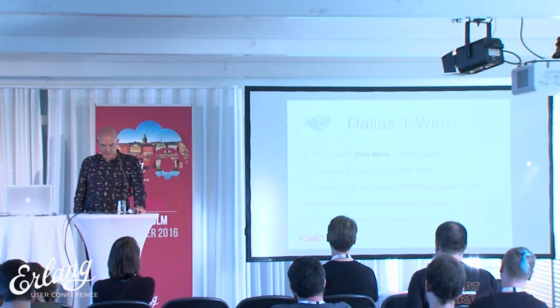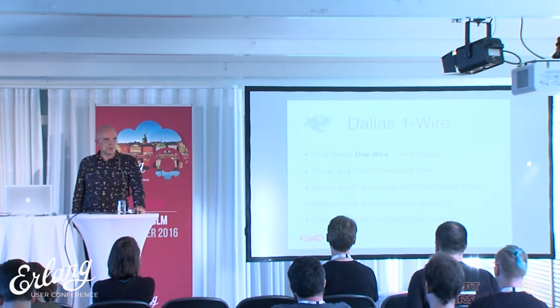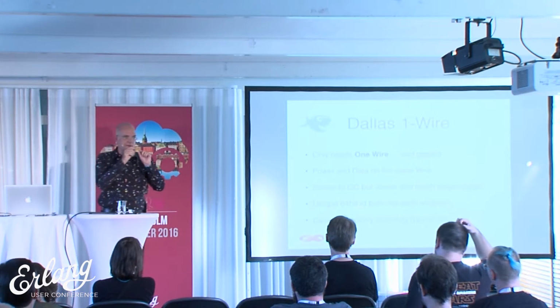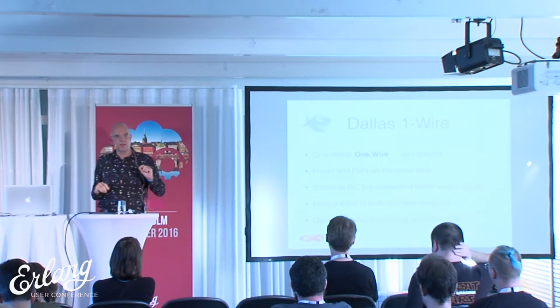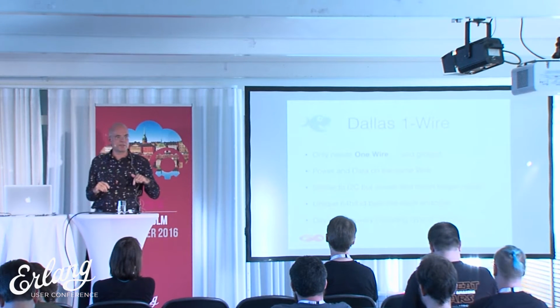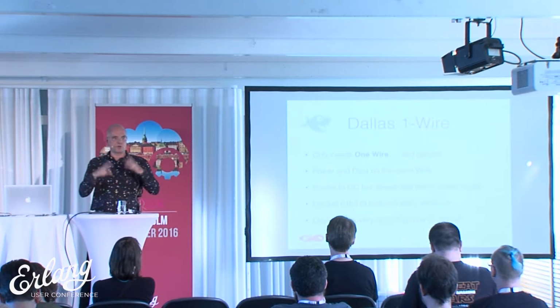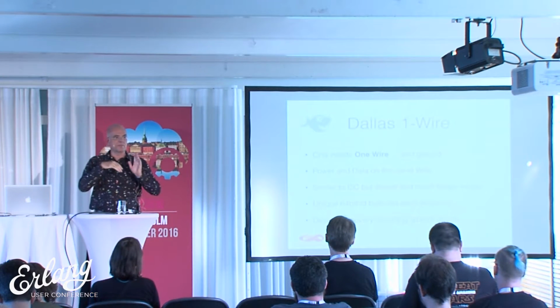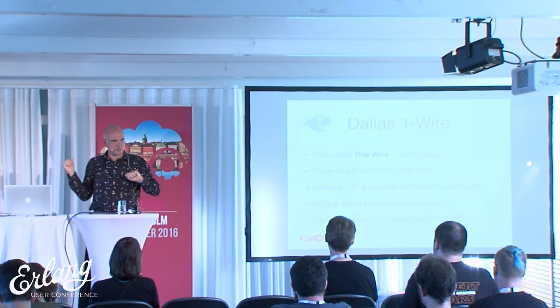There's a checksum. And what's also a neat feature is that every device, and by device I mean very small things, very small sensors, has a built-in 64-bit unique ID, which is worldwide unique. There's a discovery protocol which lets you find out what IDs are on the bus.